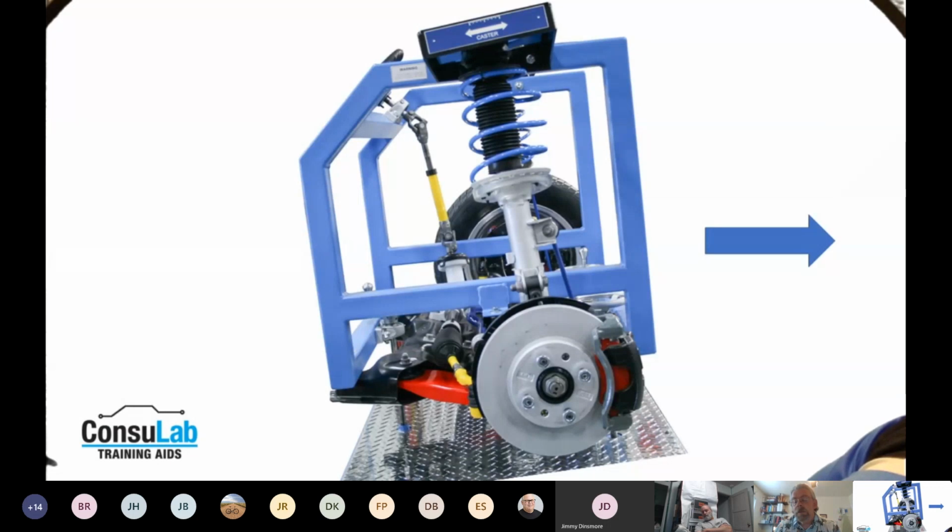In the past, I know when we used to do pickup trucks, they always used to base the caster measurement on ride height of the front. So they were, I guess, making the assumption that the rear was always the same, and then depending on what the ride height at the front was, you would adjust your caster settings. So it's been good that a lot now are getting more into the frame angle. And like I said, a lot of alignment machines now have a place to enter that frame angle.